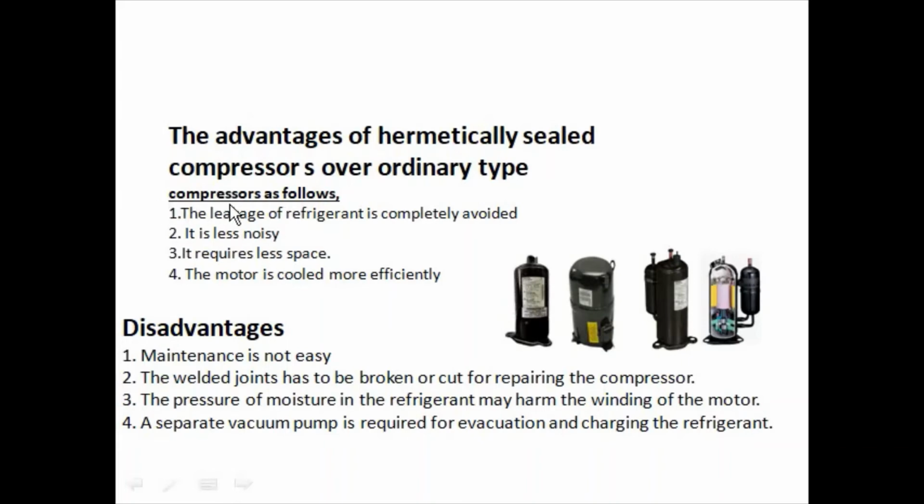These are the advantages of hermetically sealed compressor over ordinary compressor. Point 1, the leakage of refrigerant is completely avoided. Point 2, it is less noisy. Point 3, it requires less space. Point 4, the motor is cooled more efficiently.